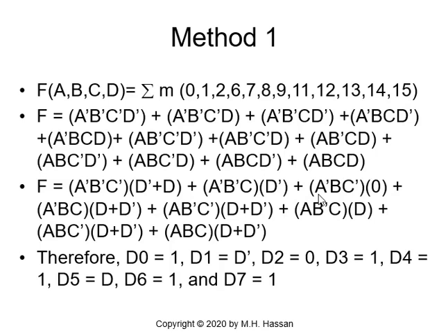We look at the minterm A prime, B, C prime. This is M2. M2 does not exist in the equation. If it does not exist, its coefficient is 0. So the data line D2 will be 0. This is M2 for the 3 variables.